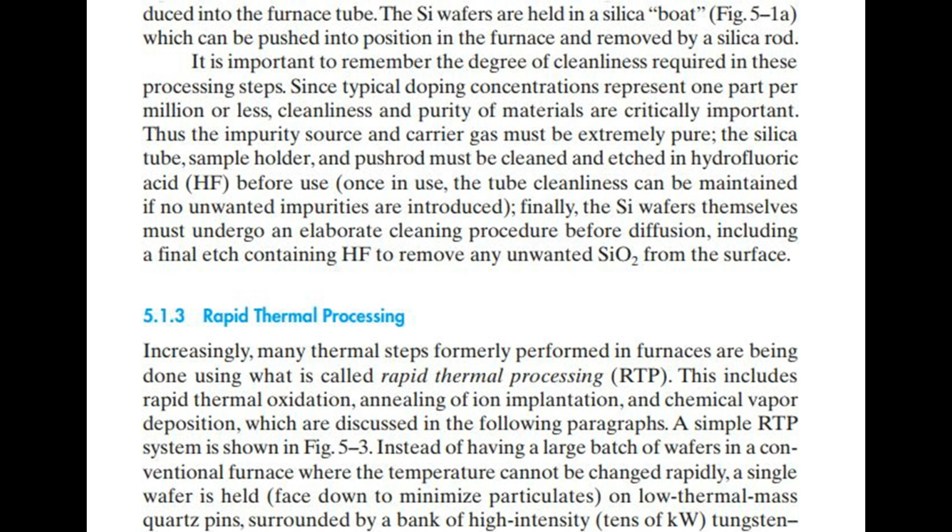It is important to remember the degree of cleanliness required in these processing steps. Since typical doping concentrations represent 1 part per million or less, cleanliness and purity of materials are critically important. Thus the impurity source and carrier gas must be extremely pure, and the silica tube, sample holder, and push rod must be cleaned and etched in hydrofluoric acid, HF, before use.